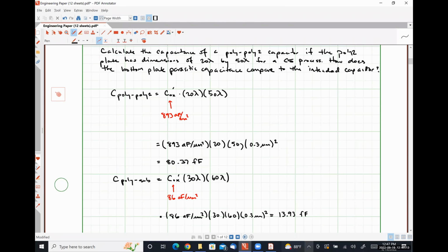All right. So let's see. Those are our poly capacitors. The only other thing that I really want to say here is, typically speaking, the poly capacitors are formed by using the doped polysilicon. So you wouldn't use the high res poly layer for a capacitor. You want to be able to push charge on and off of it pretty easily, so you don't want it to be too overly resistive.